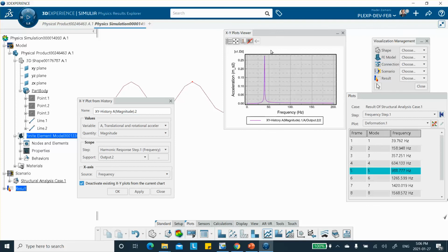Notice that we have some frequencies, and this means that around those frequencies there is resonance. In the range that I did the calculation, sweeping 0 to 200, this is the only frequency that was present. Now I didn't bother checking where the other frequency is. You can actually move the bar here to find out what that frequency is. It's right there, see that?